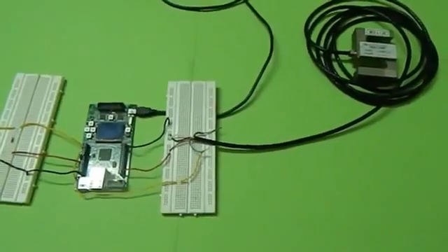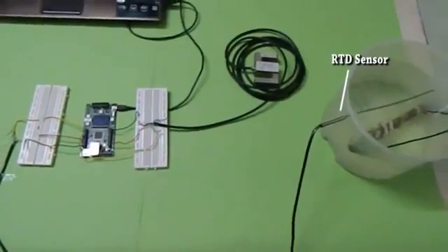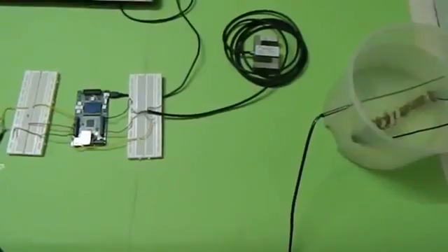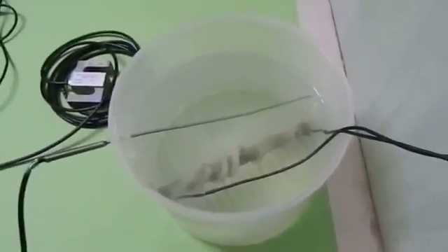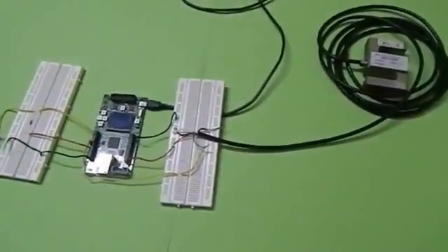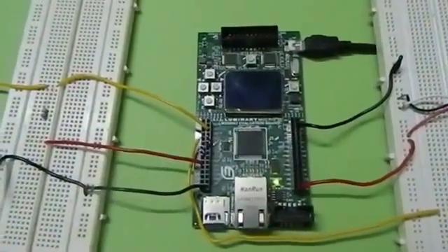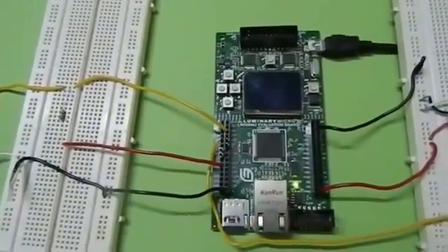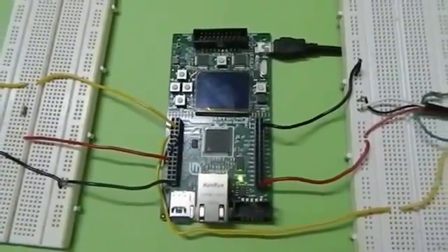We are representing our application through a tentative hardware. We are interfacing two sensors, a temperature sensor and a load cell. Our temperature sensor is placed in hot water to measure the temperature of the water. This sensor is interfaced to the microcontroller board at an analog pin which has an analog to digital converter. This data is scaled according to the datasheet of the sensor.